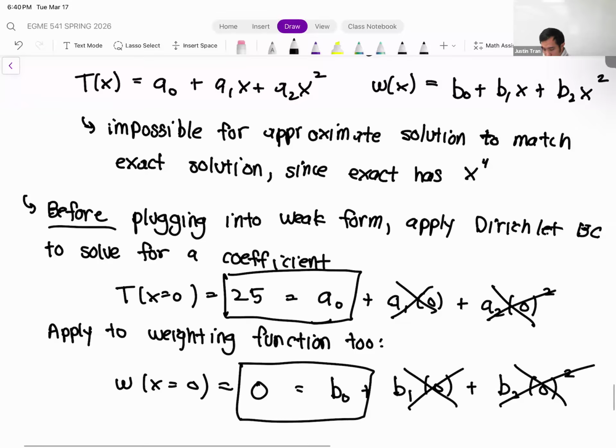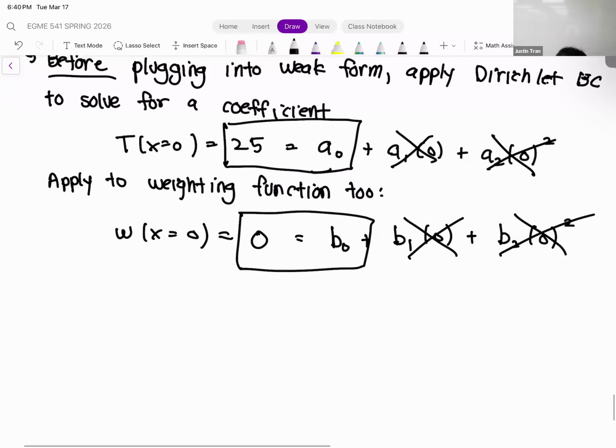Any questions on how we did that step there? Okay. We only have 5 minutes left, so I don't want to get into the weak form just yet. But before we go for today, I do want to mention a couple of wrinkles that can happen with this particular step, because I think this step can be a little bit confusing for people. For this particular problem, in a 1D problem, typically you're going to have one Dirichlet boundary condition and one Neumann boundary condition. It's technically possible to have a situation with two Dirichlet boundary conditions.